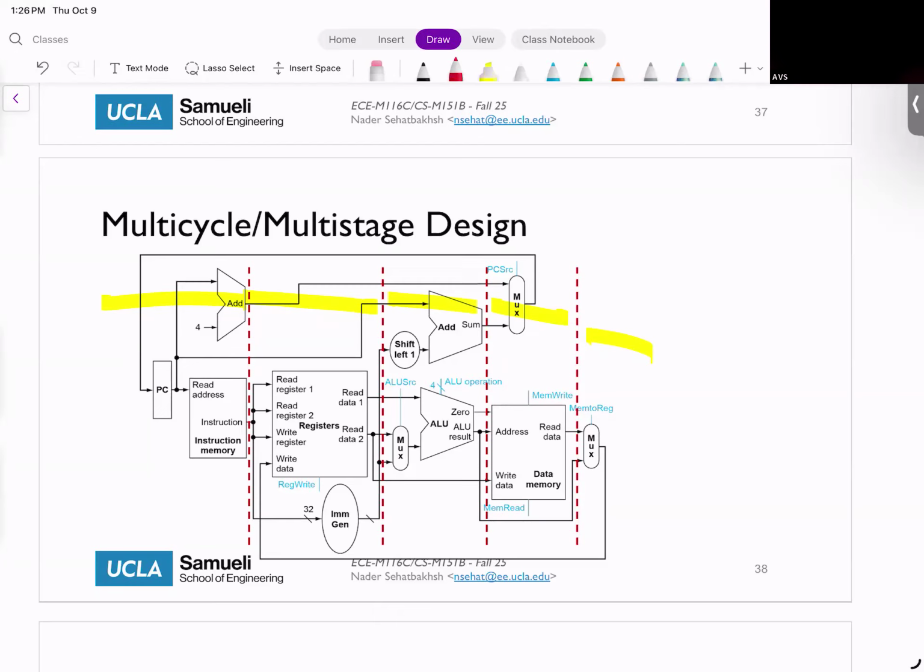So how does this help us? Remember I told you to think about your registers as gates, and the activity as the flowing of water. So essentially I'm adding more gates, okay? At every clock cycle, I'm closing the gates and opening them one by one. So the water starts from here, the charge goes to here and stops here. At the end of the cycle, things need to be stable at this point. I no longer need to wait for everything to be stable. I just need things to be stable here.